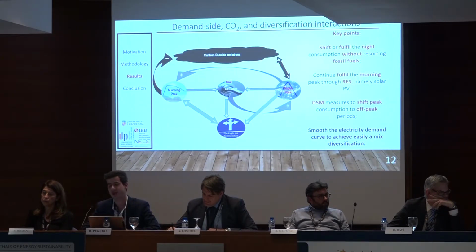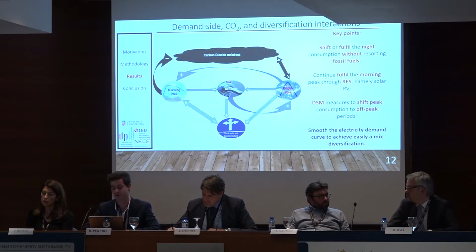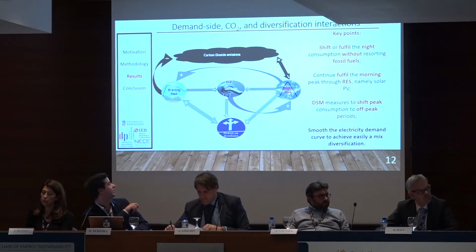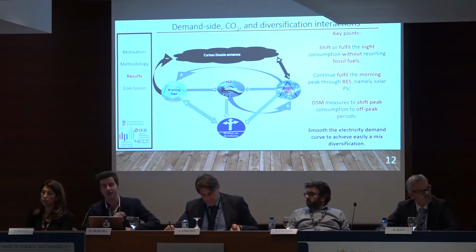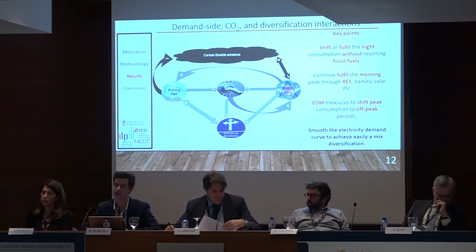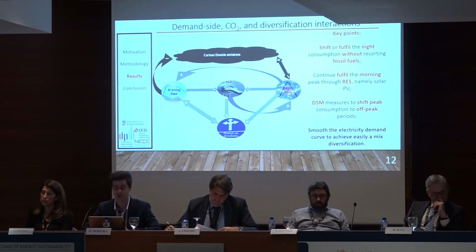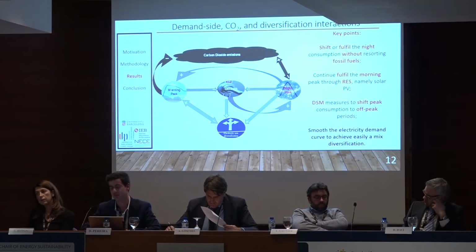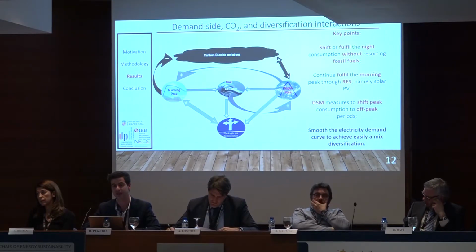So demand-side management should evolve. Firstly, stopping the load transfer from off-peak to night-peak periods. There is a huge load transfer from off-peak periods to night-peak periods, mainly caused by household consumption. So the grid has to focus on two strategies, valley filling and peak clipping, urgently.